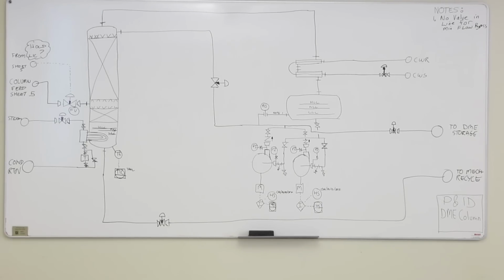So the liquid coming down into that pool is 720 kilograms an hour, and the vapor that we're driving out of there is 465. Therefore, the liquid that we're taking off the bottom of the tower, if I could make this bigger, oh, there it is, is 254. So one of those is not 10 times the other,